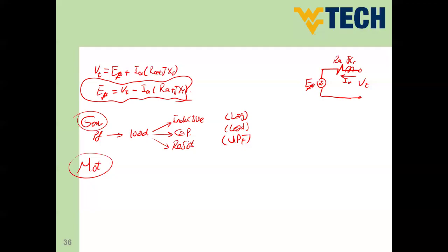Actually, this is because we have an internal source inside the machine. So the induced voltage inside the machine itself plays a role in controlling the power factor. Which means by changing the value and phase shift of the excitation voltage here, this can control the power factor of this machine.